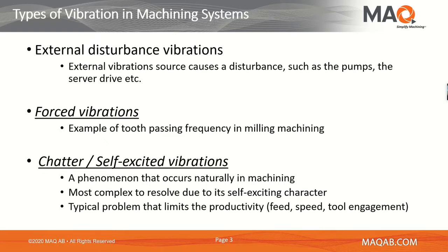And the other 2 types are categorized as the forced vibrations. One typical example is the tooth passing frequency in milling applications, where the cutting edge gets engaged and disengaged with the workpiece, and that excites a vibration in the machine tool system.